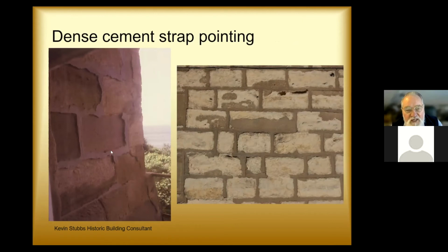Again, repointing. One questions whether this stonework actually did need repointing. The joints are very fine. It's facing the sea, as you can see here, and it's been rather ham-fistedly repointed, question mark, with a cement mortar.